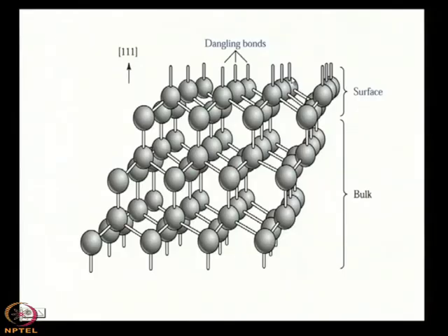One part is oxidation. Another important disadvantage is the processing technology. Silicon you can dope very easily, you can diffuse, ion implantation is done, photolithography, all processing technology is very matured. You can handle large wafers. In gallium arsenide or indium phosphide you cannot make them. Large wafers are very difficult to handle because they are brittle in nature, they are very soft. So, those are the disadvantages. Though it has many advantages, it has disadvantages as well.